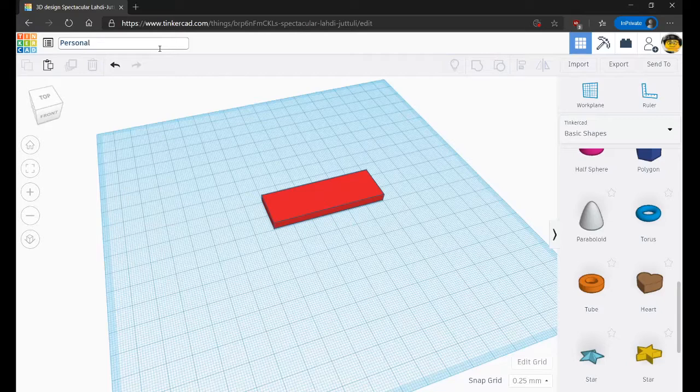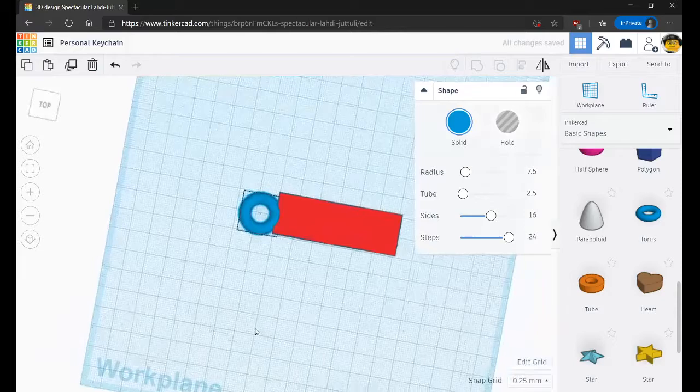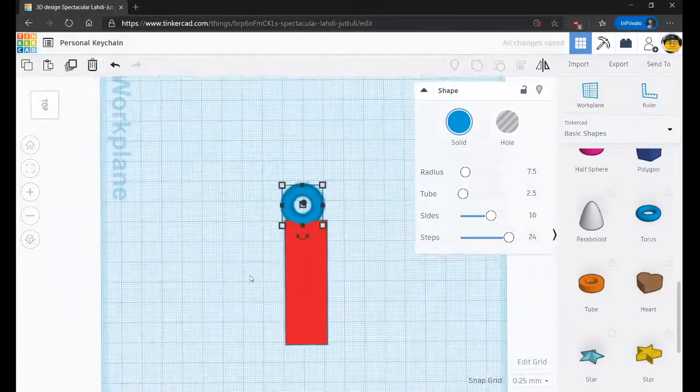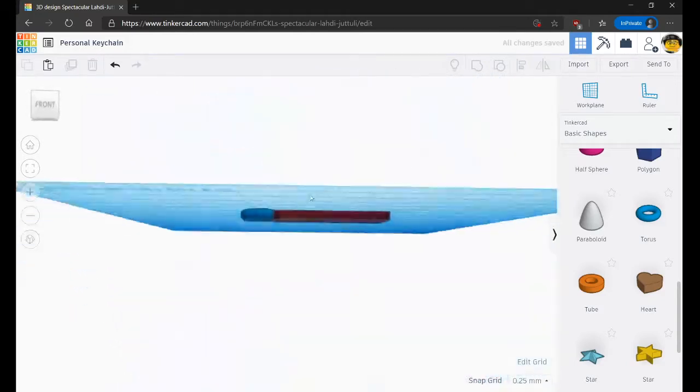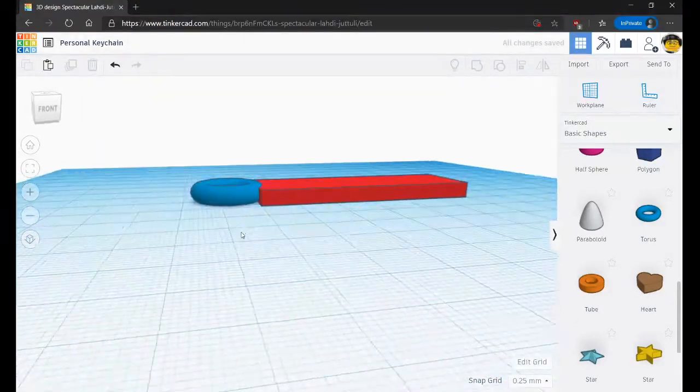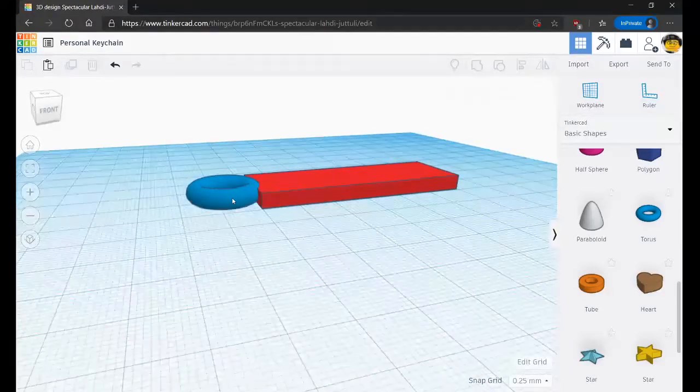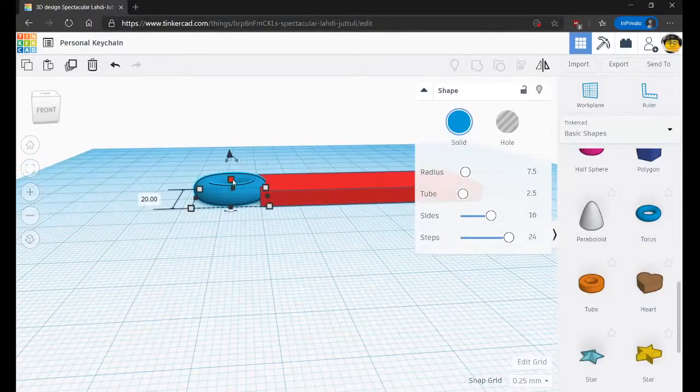Now, on the right hand side in the object pane, let's click on the torus or the little donut shape and go ahead and insert it where it's overlapping our base. You can use the keyboard to adjust to make sure it's centered. Again, here I'm using the camera angle to make sure that it is centered by clicking, making sure I'm on the top view. But you'll notice here that the objects overlap, and we want to adjust the height so that they're both about the same thickness.